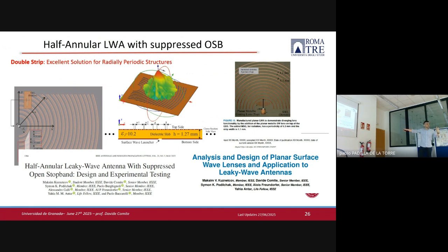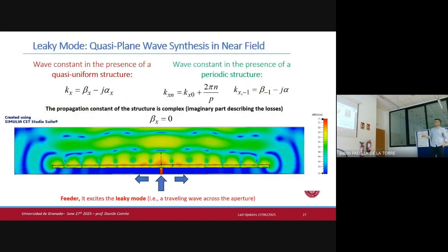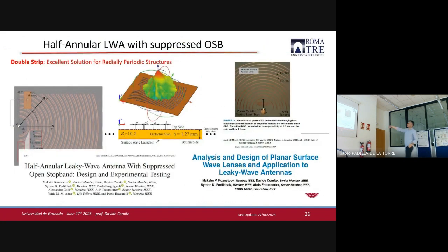PCB, much thinner than a fabricated cavity antenna. Here the thickness of this PCB is much smaller than λ/2. So it's not thick, and it's planar and well integrated. Then you can use lenses here to try to adjust the illumination a little bit. So you can use different configurations.